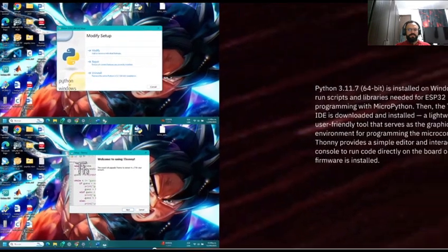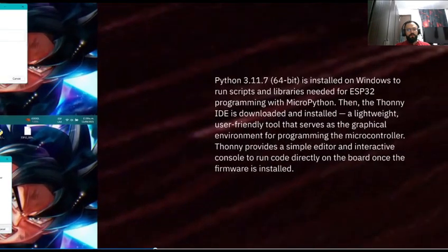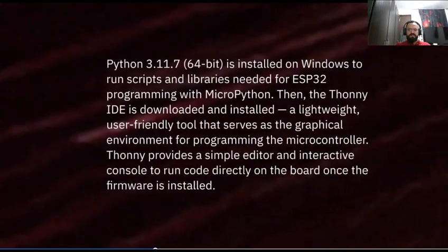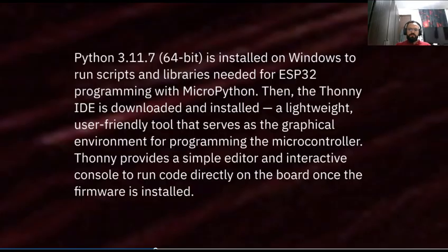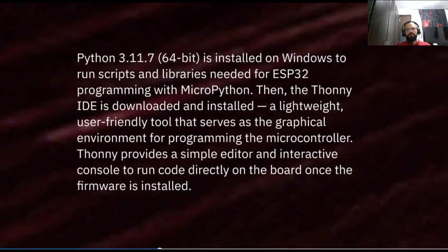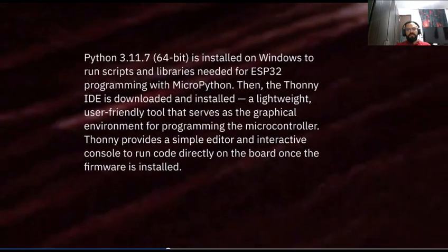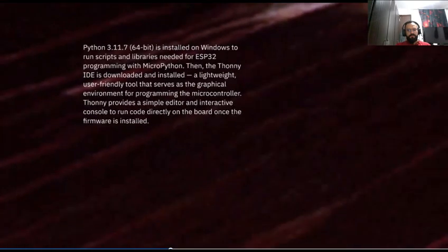In part 3, materials and electronic components, I talk about the hardware implementation of our project, which is based on several key components. The central device in the transmitter node is the ESP32 microcontroller, which includes Wi-Fi, Bluetooth, dual-core processing, and multiple communication protocols such as I2C, SPI, and UART.